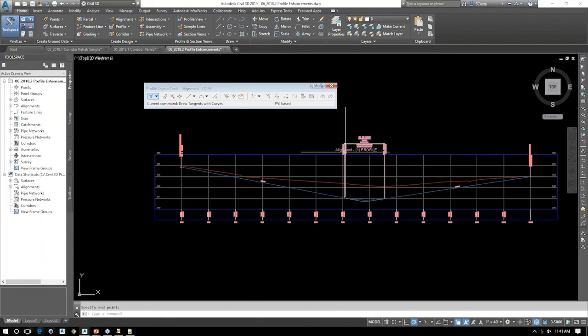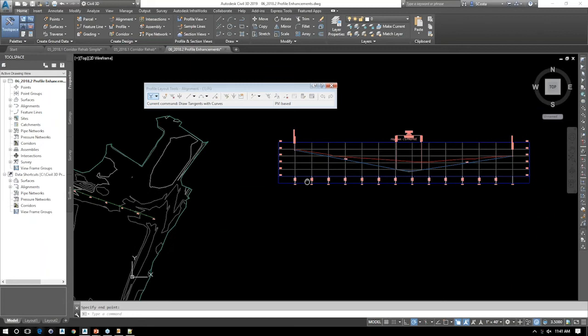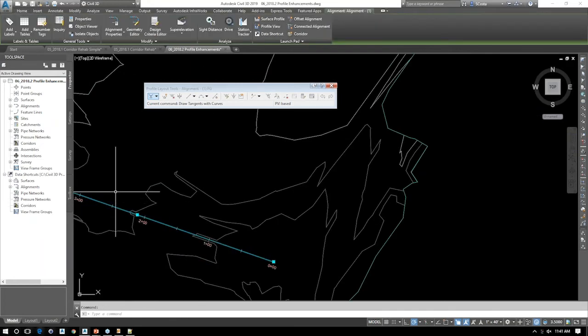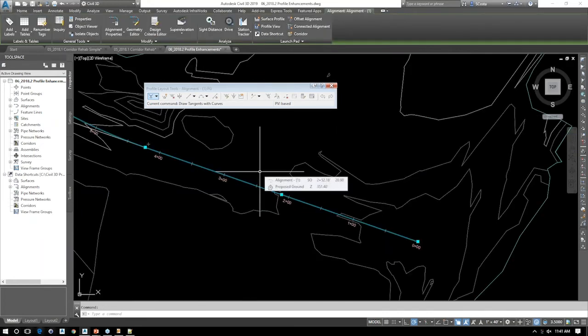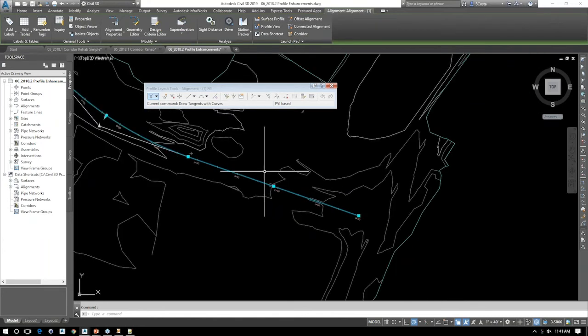Civil 3D. What I'll also point out is that for offset alignments, you no longer have to deal with, what's the word I'm looking for? If you had a profile curve that you were offsetting, that's a parabola. Civil 3D in previous versions tessellated that parabola into individual segments. So the new feature gives you the ability to create an actual parabola offset profile.